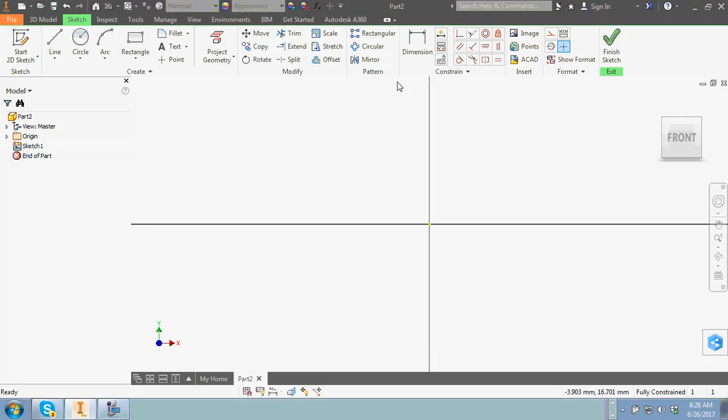We're going to go back to our part, and let's click on rectangle. When I click on rectangle, you're going to see that when I click on my origin, as I drag out, I haven't placed the rectangle, I'm just dragging out. Notice how the 11 millimeters here is highlighted in blue. We had 3.5 centimeters wide, so I'm going to say 3.5. Now I'm in millimeters, we want centimeters, so I can just hit space and hit CM. You'll notice it goes from red when I hit the letter C, and then once I hit M, it understands I want to do centimeters.